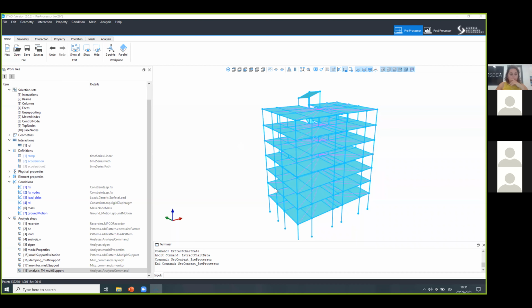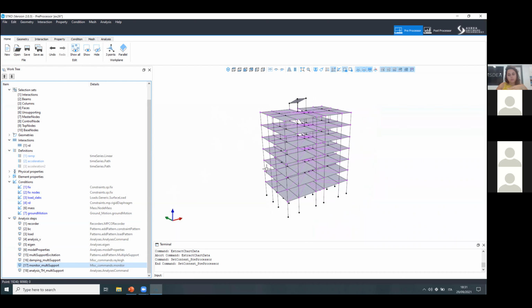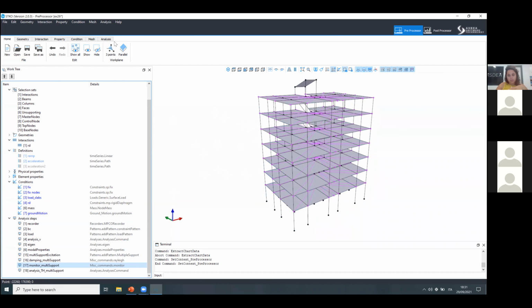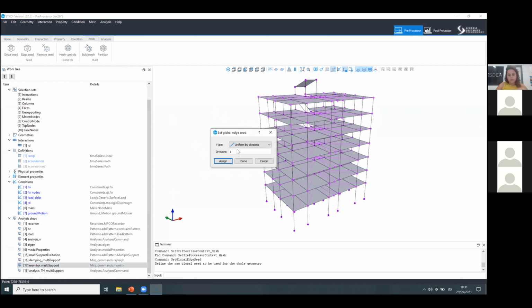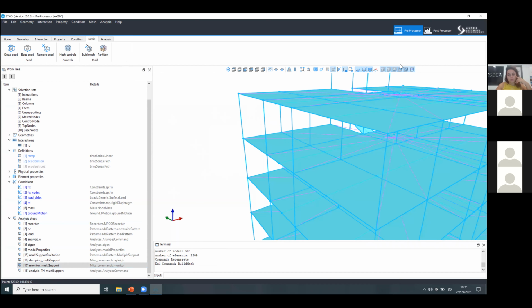Okay, so for example, using the monitor, you can monitor, but you cannot monitor nodes of the mesh. In STKO, in this case the mesh is just one, but if we divide our structure more, within the mesh we're not able to select a node that is not in the geometry. Exactly, the monitoring. So this node here, we cannot select it for a monitor. So if the node is not part of the geometry, you cannot do this.